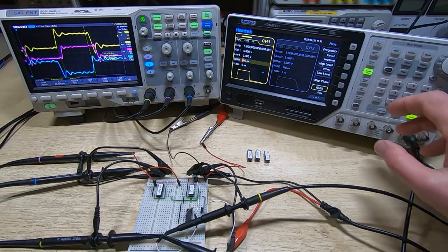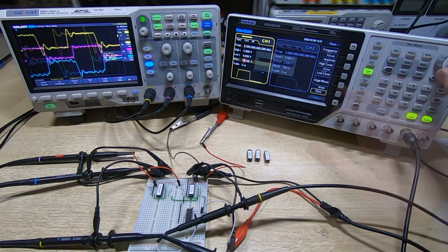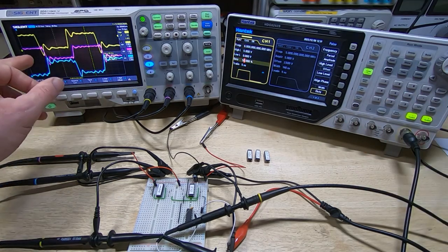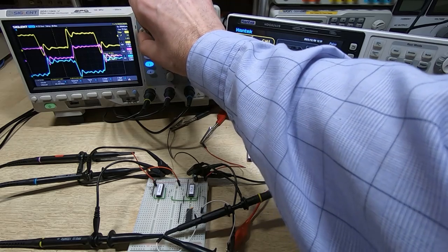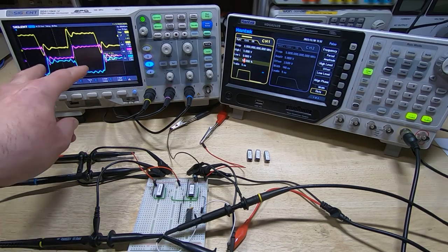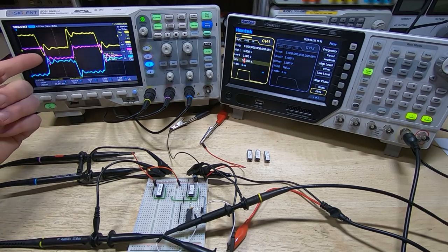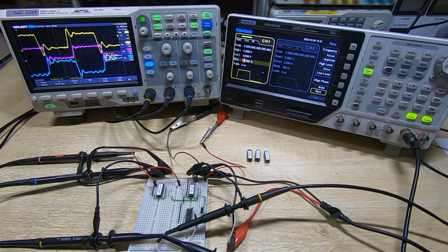If we change and go up to 6 megahertz, you'll see that we get an even bigger problem. Okay, so you can see now that we have an issue here, that the falling edge of our failing device is now outside of that particular phase of the main clock. So whatever process it was supposed to have completed, it's failed to do that, and we're now into whatever the next phase of the process would be on the board. So this will almost certainly cause a problem, but you can see the purple trace has responded quickly. The falling edge is well within the clock cycle, even at this speed.